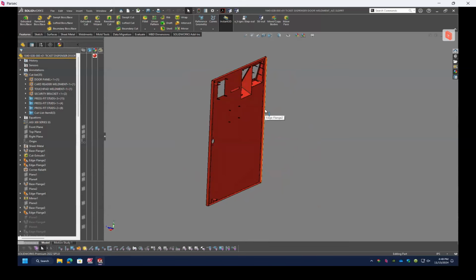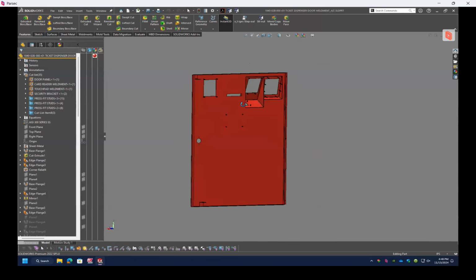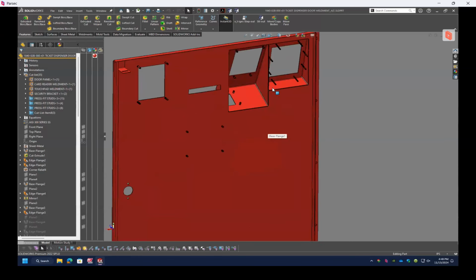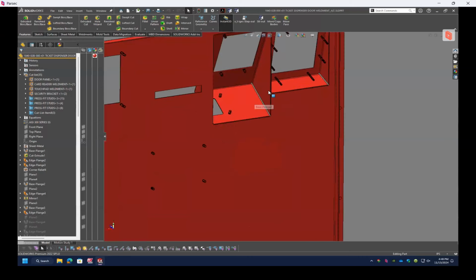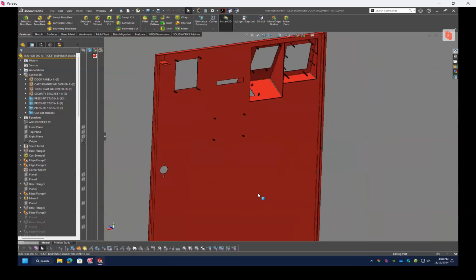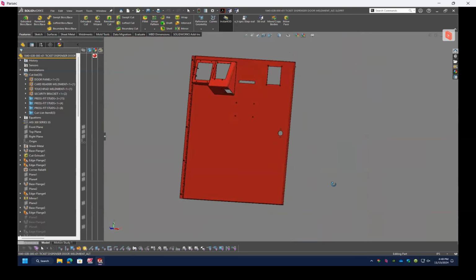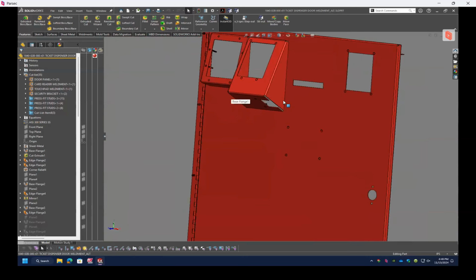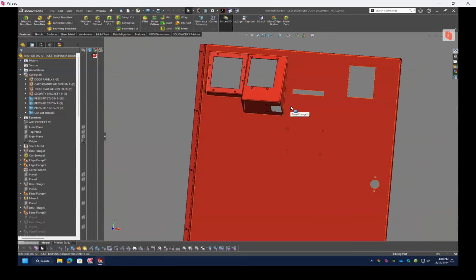But this then has various other parts bolted on. So some of those parts were modeled in here, but this really made sense as being a critical main weldment and done as a multi-body because so many of these features are tied together and relate to one another. So if we need to change the whole pattern or size of this cutout, the panel would just need to correspondingly change.